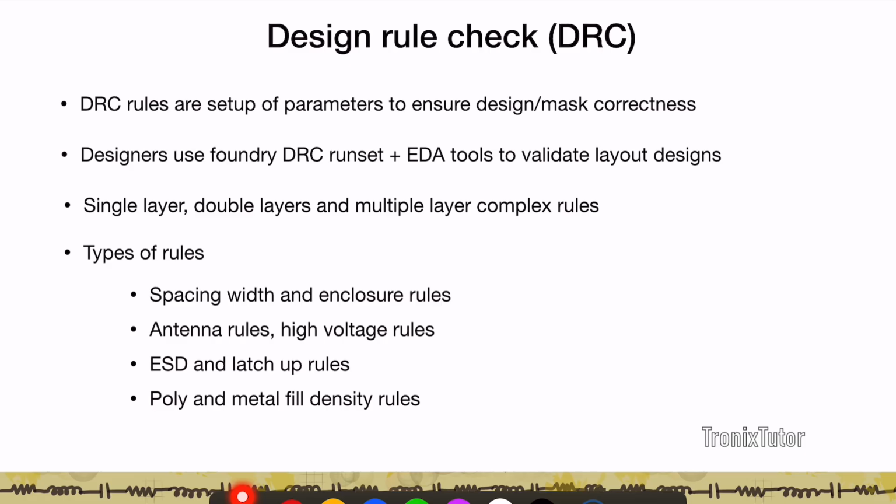trench is, if you will. And so you want to ensure that in the worst case, or in the narrowest metal trench, the process that you've developed for this particular node is able to fill in that metal and not cause any voids, because a void in the metal line essentially leads to a high resistance, right? So there are rules related to what is the smallest width one can draw in the metal line and so on and so forth. Similarly, as I mentioned with the poly and active, you have enclosure rules, how certain layers have to interact with other layers to ensure that the device functionality is not lost.